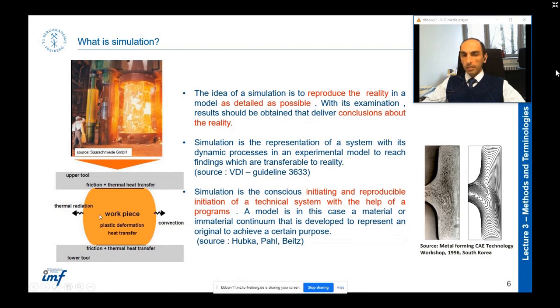It means that there is no porosity inside, but you know that in reality there is. In such a big block of steel, of course, there is segregation, there is inhomogeneity, there is porosity, but in simulation, we ignore these small things because they would not affect the result that much.